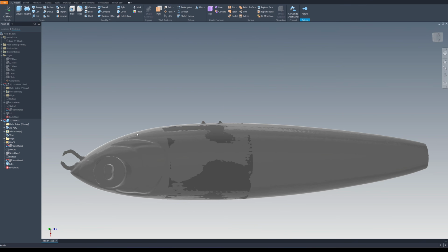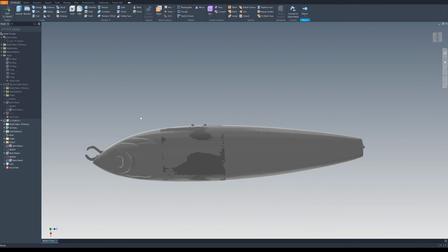If you want to split it, for example, if I want to split this fishing rod into 2 parts, I need to use the split command and rebuild it again, and then I need to export the split parts into an assembly, which is quite complicated. For example, if you want to create a dovetail, it will be more difficult to create mechanical joints because you are designing inside of the part environment.